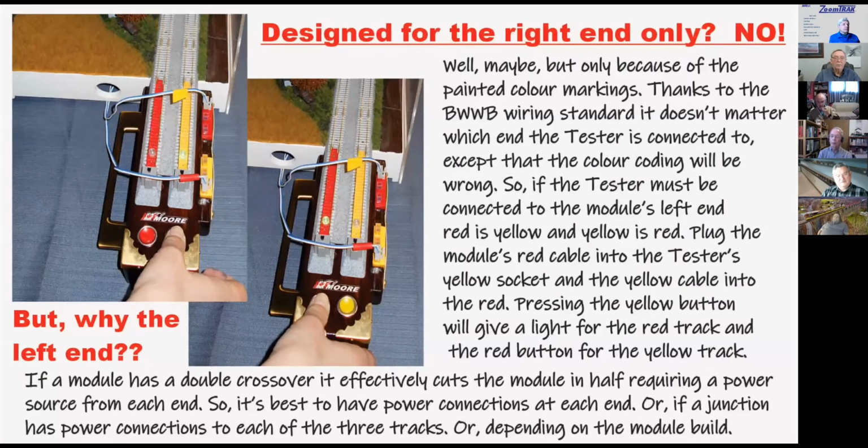Now, designed for the right end only? No, not really. But, well, maybe only because of the painted color markings. Thanks to the blue, white, white, blue wiring standard, it doesn't matter which end the tester is connected to, except that the color coding will be wrong.